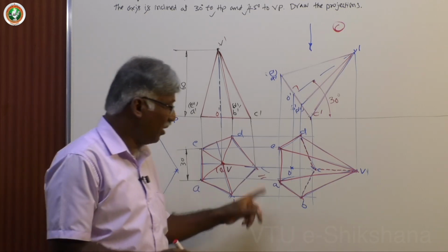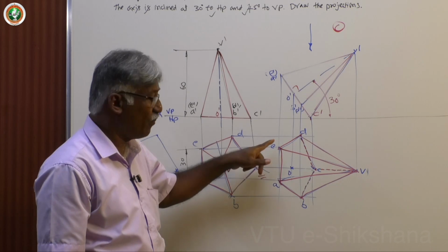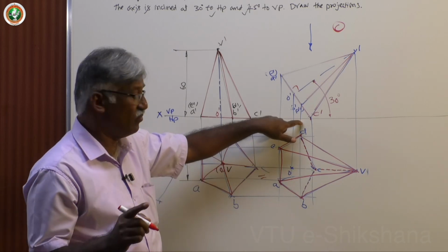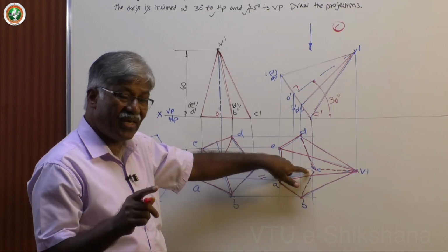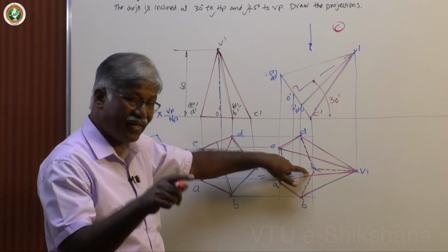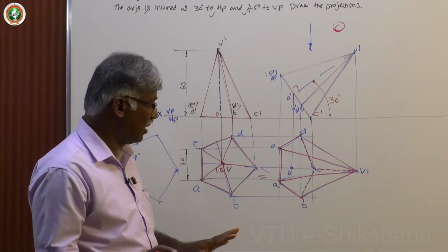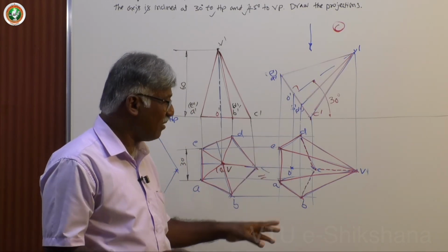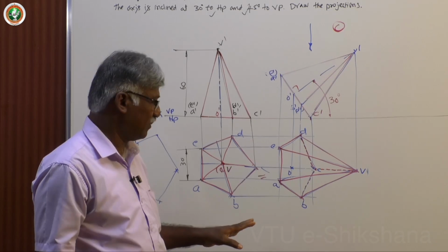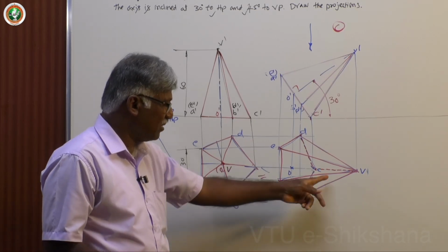Okay. Now, I will repeat: if you look from this direction to complete the second figure top view, C is the farthest item from you, that is not visible, and any number of edges, either slant edge or base edge, connecting to that are not visible. So, hidden lines. Rest of the lines all are dark, and all boundary lines are dark, that is always there. Okay. Next, we have completed all edges, visible and invisible.